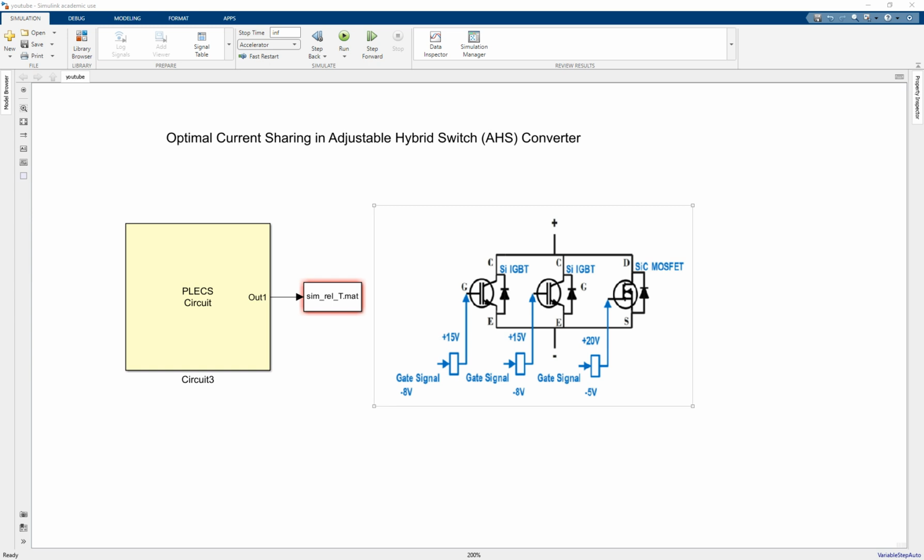And you can also have more than two IGBTs, like two groups or one more group and something like this. So more complicated configurations. This is also known as hybrid, simple hybrid. But the difference here is that this time we assume that the gate signals can be actually independent of one another. So in other words, you can activate or deactivate IGBT and MOSFET. Whereas in hybrid, you usually activate both at the same time and deactivate at the same time. So they have the same signal at the gate drive.